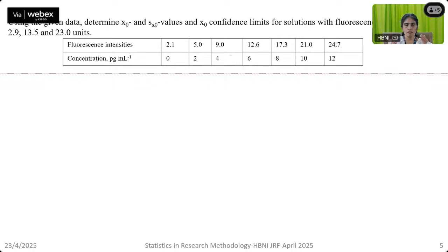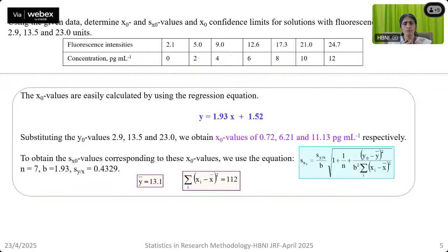As I told you, whenever we do the calibration function for concentration calculation, see to it that it includes the signal within the range. If not, shift the calibration and redo the entire exercise. You can give it a try and arrive at the slope and intercept. Easy calculation is available; any software you can use.